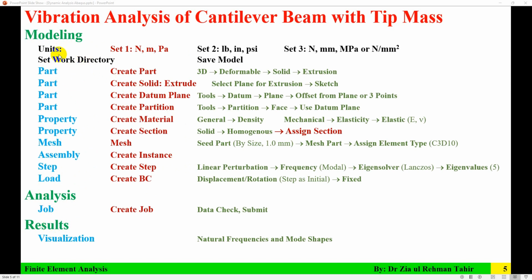So first things first, there are no defined units in Abaqus CAE, so you have to set your own units. A set of units you can use is Newton, meter, Pascal, or pound, inch, psi, or Newton, millimeter, megapascal.